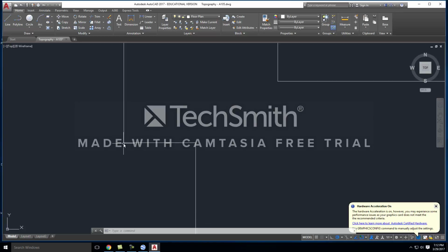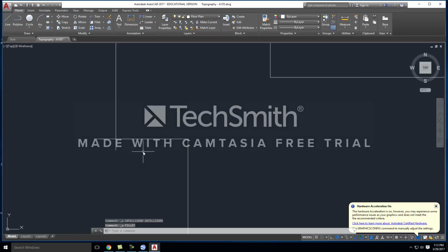The reason it gave me a nice clean corner and didn't give me something like this is because the radius is currently set to 0. That's the nice thing about fillet: it does basically two things. It gives me a nice clean 90-degree corner if that's what I want, but it also gives me an arced corner, okay? So let's look at how we would get the arced corner. Let's go back to what we have.